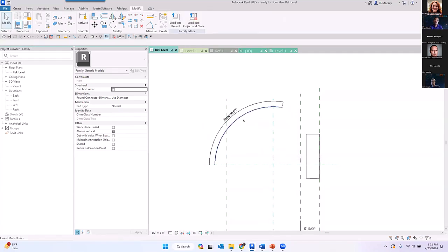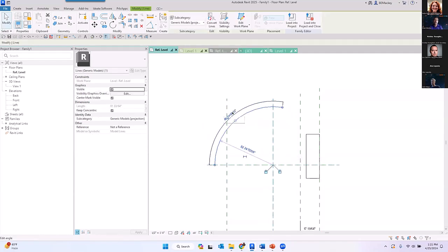By aligning and locking the endpoint of that curve, now when I change this angle to be like 77 degrees, cool, you're noticing it's going one direction or the other. Also, you're going to notice that if I start making those values greater, this is constrained. I'm doing the angle wrapping around. I am never going to have this family flip.